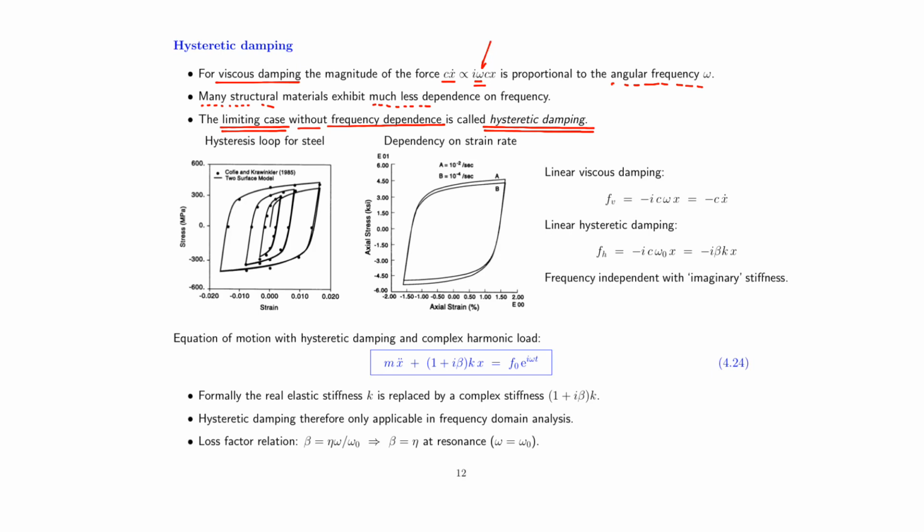I made some experiments to indicate this. A typical hysteretic damping model is seen in the figure to the left, where we start out the experiment at rest, and then we begin cycling the structural model in a constant loop. We can see that we have different loops in here, and they change depending on some properties. On the right-hand figure, it's investigated how this changes with respect to the cycling frequency.